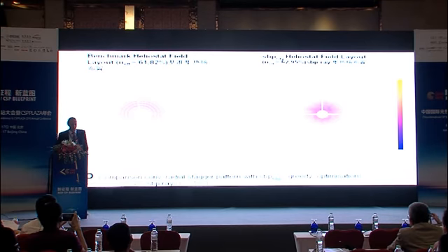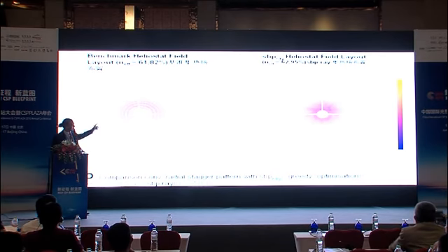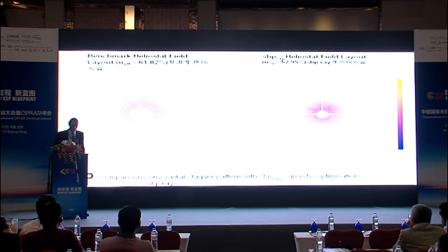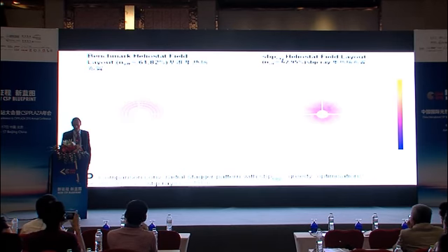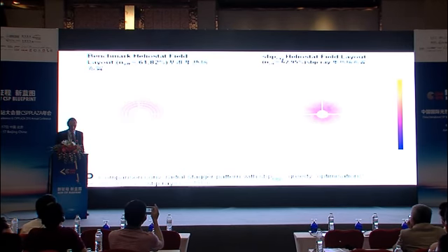So if you look at the left side, that's a standard radial pattern system, and you can recognize the radial layout, and then the radial layout always steps and has slip roads, where the setup of the heliostats is changed again, and always here you have some gaps in between. But that's the standard method of how you do that. With optimizing this to an extreme, you get for this specific location to 61.8% solar efficiency over the year.